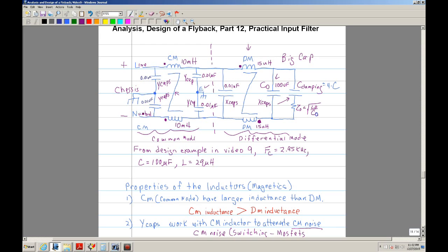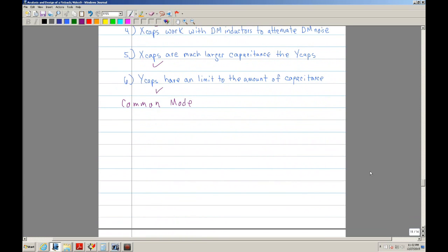If you short those lines together, then you're shorting this cap right there. In other words, if you connect the line to the neutral, that shorts across this cap, it shorts across this cap, and it shorts across this cap. Basically you don't have anything. So let's draw the model and see if it makes sense. In shorting the line, we can say that this is L, dash N.